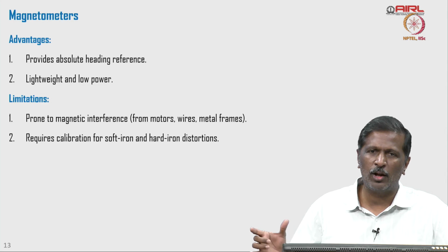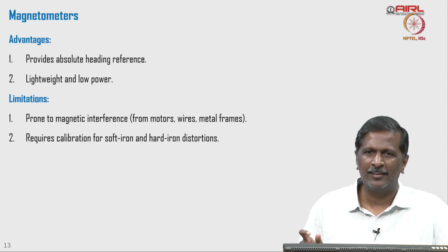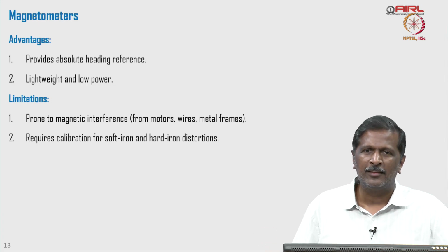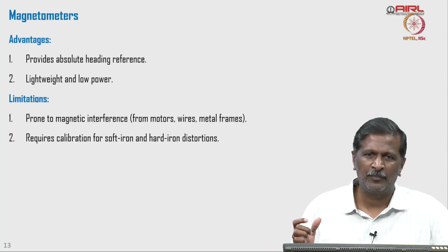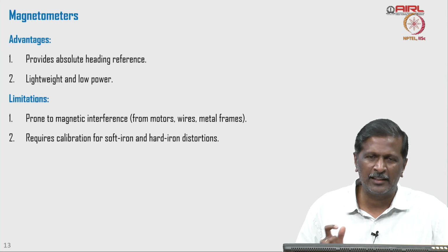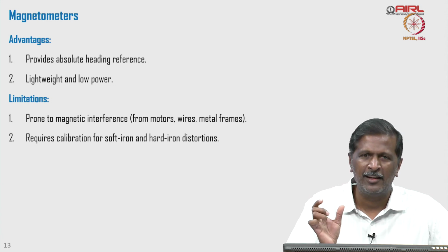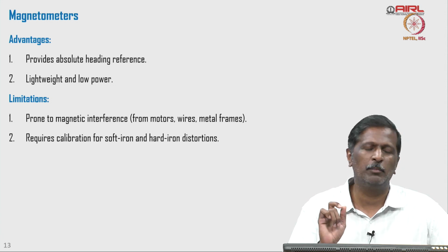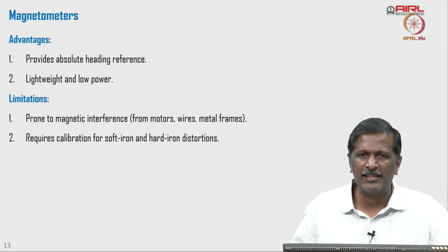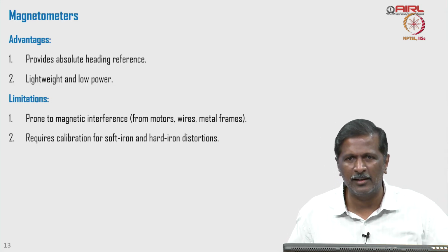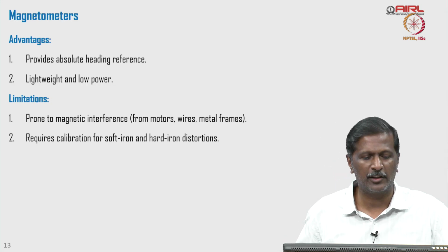When you have a small onboard computer, right, and you are connecting the computer to external sensors like a camera and LiDAR, they do produce a magnetic field at that point. For example, USB 2 or something you are using could create a magnetic field. So where this particular sensor is located plays an important role. We have to minimize as much as possible the interference from magnetic fields. If there is a power line, and the drone is flying close to the power line, it gets influenced by the magnetic field around it, right.